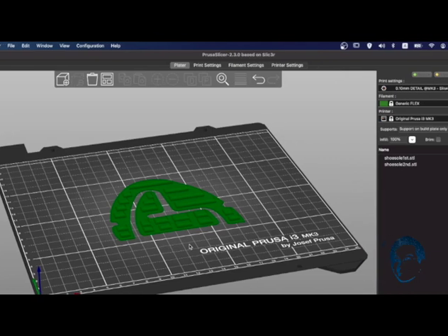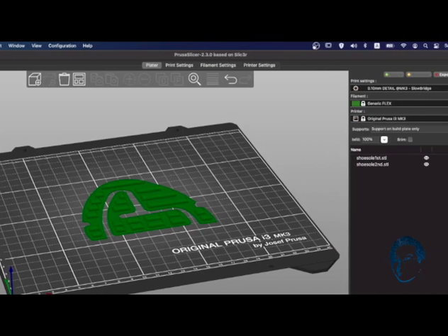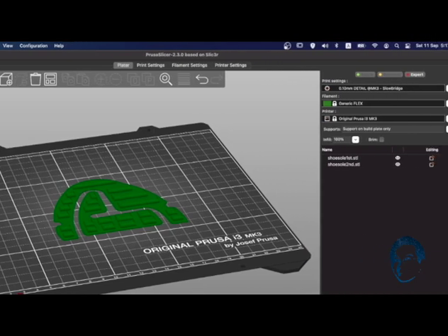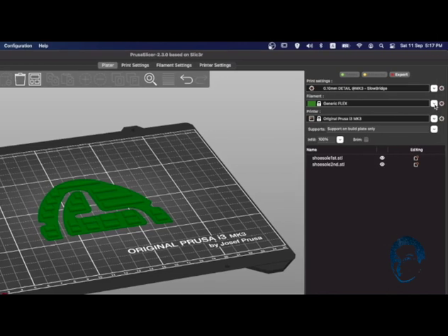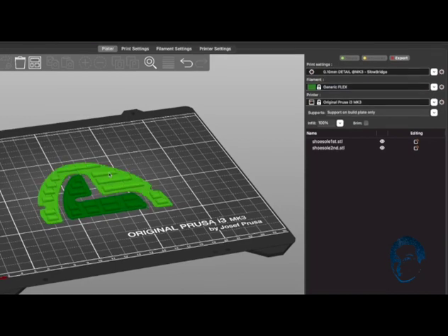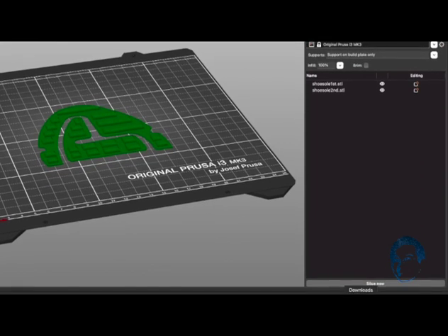Alright, so to print the outsole, we require the flex filament, which is TPU or TPE. Okay, we're going to do 100% fill so that it's durable when the actual thing is printed. Alright, that's all we need to do over here. The next step is to slice it.